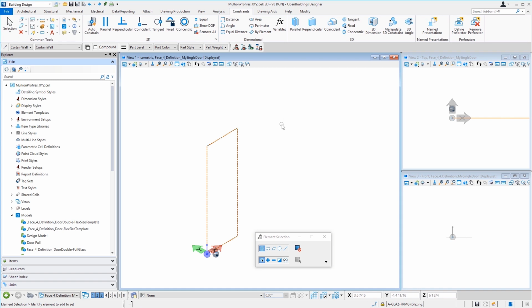Let's undo that. Now, another thing I want to constrain about this rectangle is that these corners remain perpendicular. You saw how here I was able to move that vertex, and now I have non-perpendicular corners, and that really wouldn't work for a door. So we're going to use our perpendicular constraint, and I'm going to constrain 3 corners. And if I have 3 corners constrained perpendicular, then the 4th will also be perpendicular. So that gets our rectangle constrained that represents our door panel.